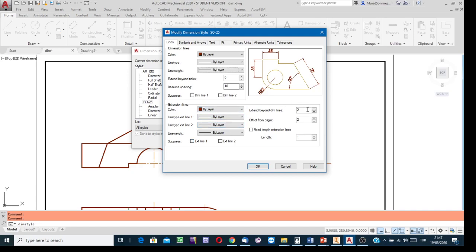And then this part of the dialog box. Remember, extension lines start from the limiting points of the feature. The dimension is for that feature, for showing the size of the feature. How? At the beginning of extension lines, leave an empty space in the order of a few millimeters, depending on the size of the projection: 1 millimeter, 2 millimeters, 3 millimeters, or a little bit more. In this example, the space at the beginning of the extension line is 2 millimeters by me.